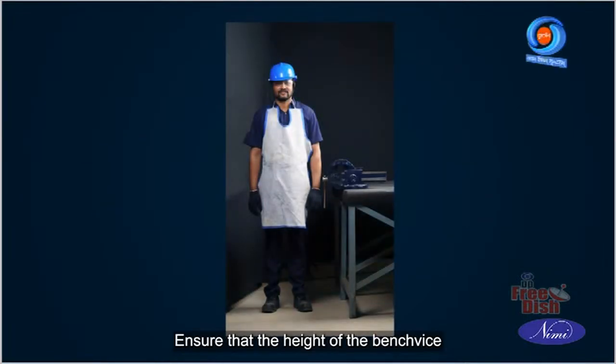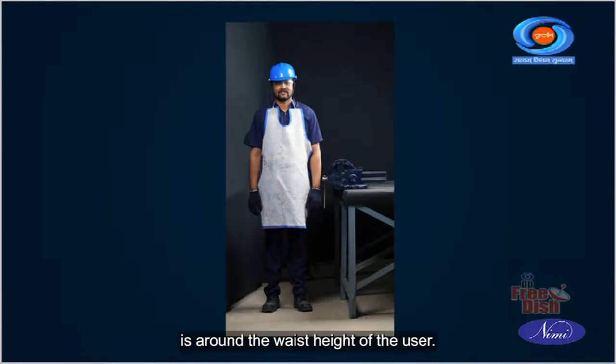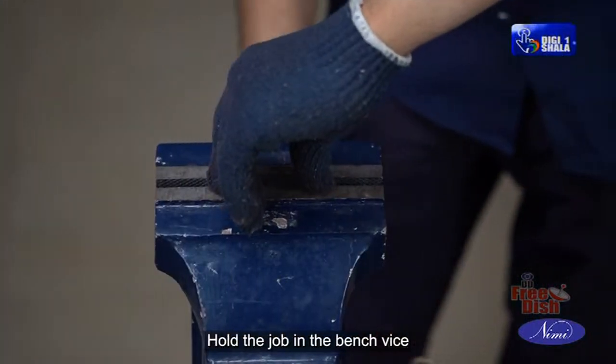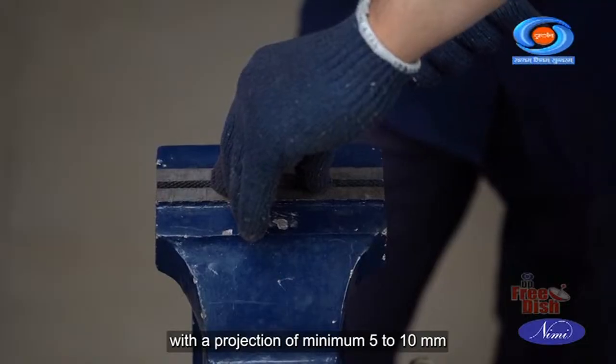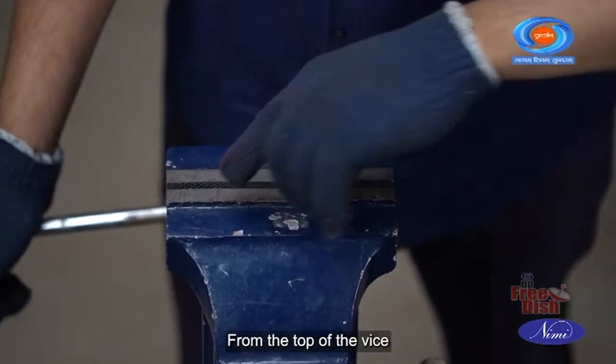Ensure that the height of the bench vise is around the waist height of the user. Hold the job in the bench vise with a projection of minimum 5 to 10 mm from the top of the vise.